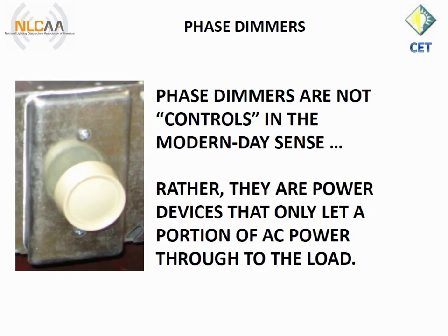The minimum functional requirement for a dimmer under Title 20 is that it be able to reduce the dimming switch leg, the dimming power leg, by 65% power in a lighting control scenario. This will typically not meet your design requirements for the code. More on this in a bit.